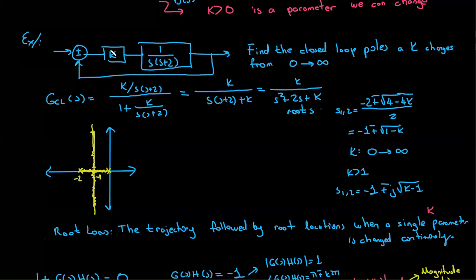And one might ask you, for example, can you achieve a certain settling time or a certain overshoot value by changing this k value from 0 to infinity for this plant? Can you achieve, for example, some settling time which corresponds to the pole locations over here by changing the k values from 0 to infinity?